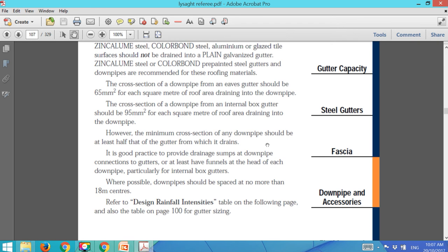Surely then there's a center requirement as well. The center requirement is really to do with where you can get it down to the ground. Surely, I don't know, with residential rainfall catchment, every 12 meters you need to have a downpipe, and it needs to catch 52 square meters of roof per downpipe. That's right, but with domestic situations, you're also using standard downpipes and standard gutters. So when you're designing it yourself, it really frees up a lot of stuff. All those rule of thumb type things for domestic things are geared towards domestic rainwater products, right?